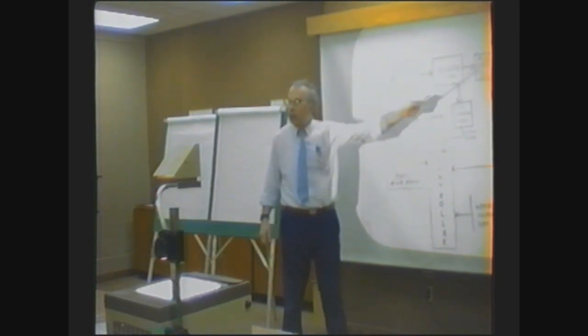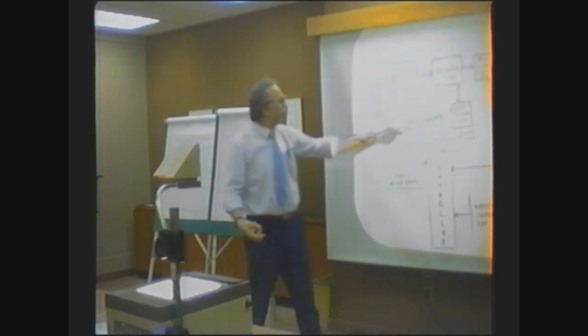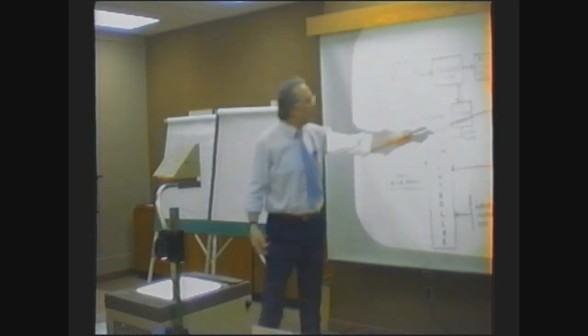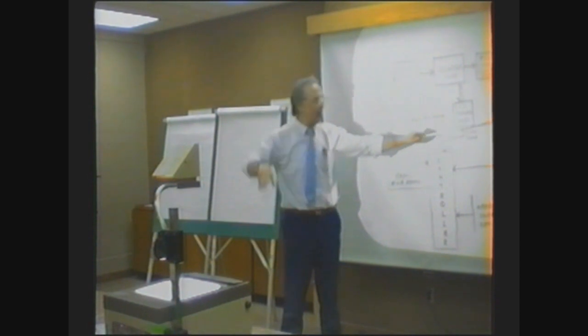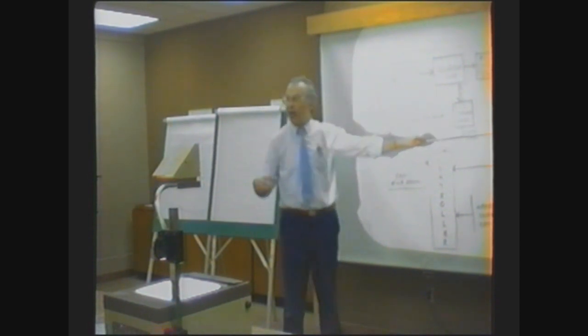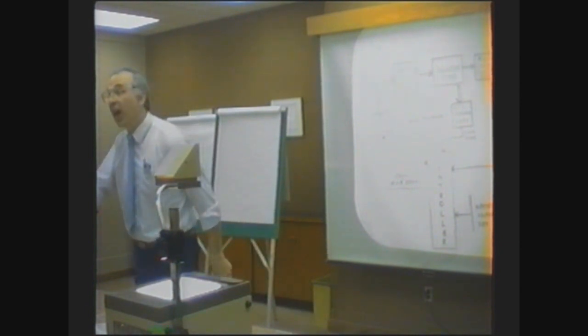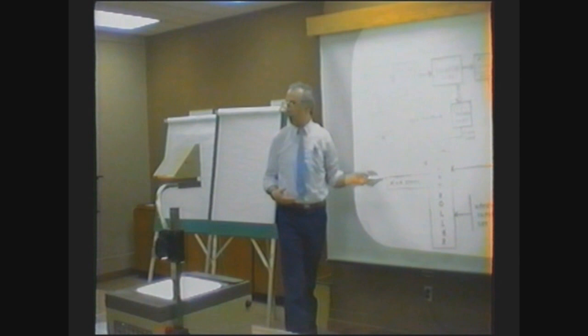The electronic system of the neutron chamber extracts three variables concerning the same entity, the flux: the linear flux, the logarithm of the flux, and the log rate, which is the rate of change of the flux in unit time. Those are also inputted to the programming controller.